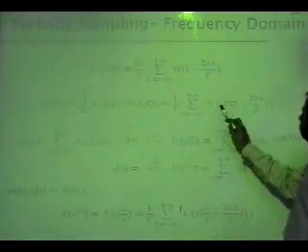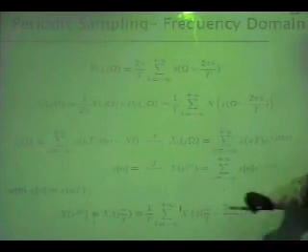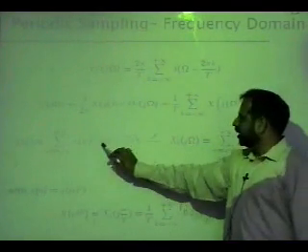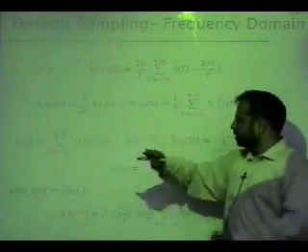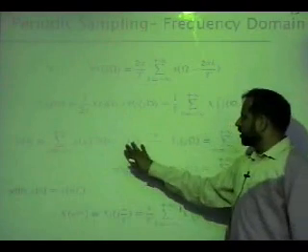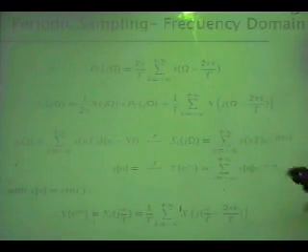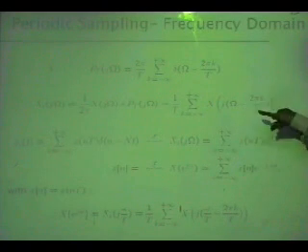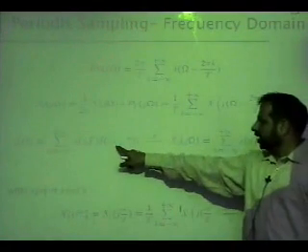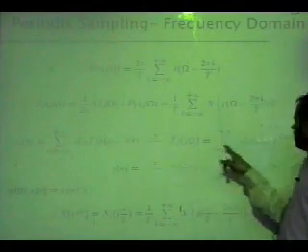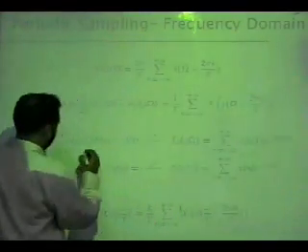Once you convolve these, you make copies of X at every 2πk over capital T. This is in the time domain, x[n]δ(t − nT), where the magnitude at every location of the impulse is tailored accordingly, and in the frequency domain, if you take the Fourier transform of this, the Fourier transform of δ(t − nT) is exponential of −jΩnT. So there is yet another way of looking at the expression.